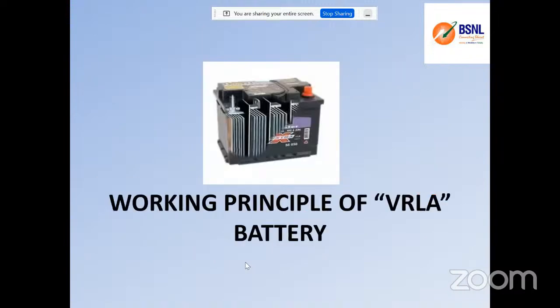Now let us come to the industry part. In our industry, we are not using the conventional because it needs a lot of manpower and maintenance and spillover environments and other things are required. So we are not using the conventional batteries in our industries. We are using a new technology called VRLA batteries, valve regulated lead acid batteries. Here the electrodes and electrolytes are the same. They are going to be the same sulphuric acid and lead, but there is a technology introduced so that the gassing will not happen.